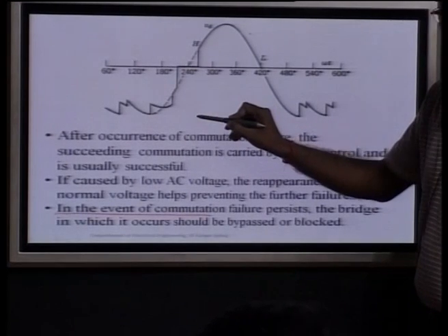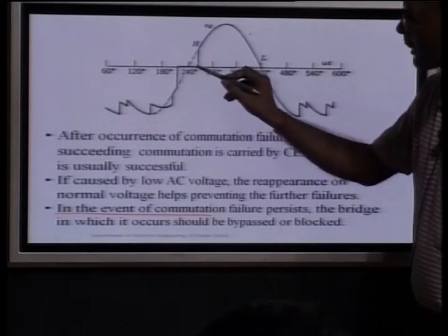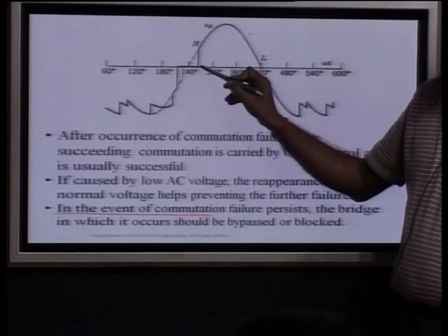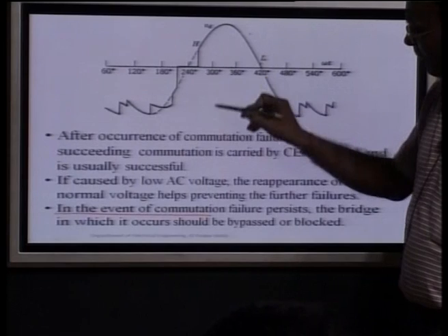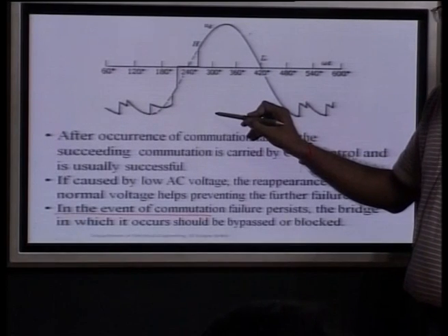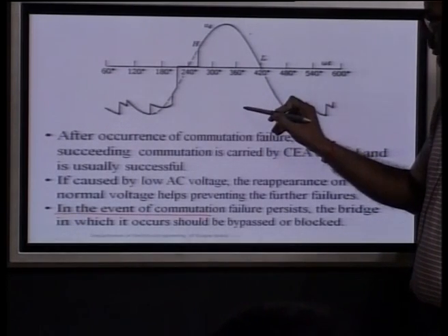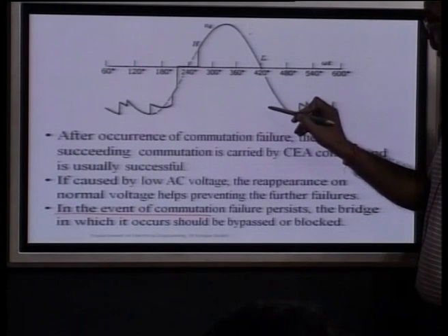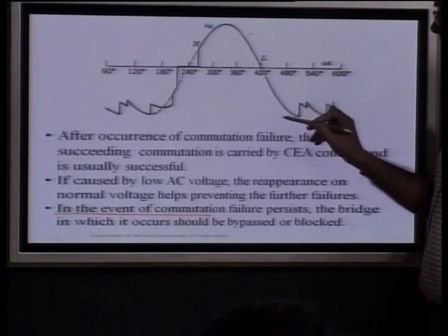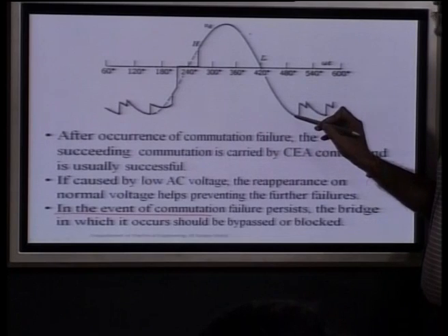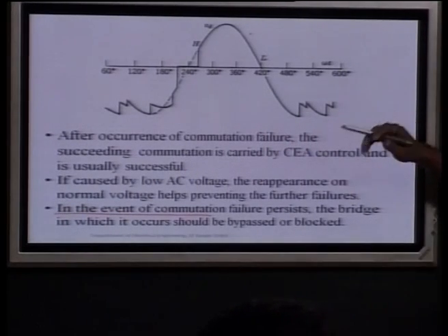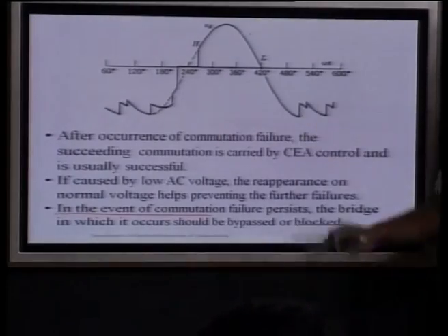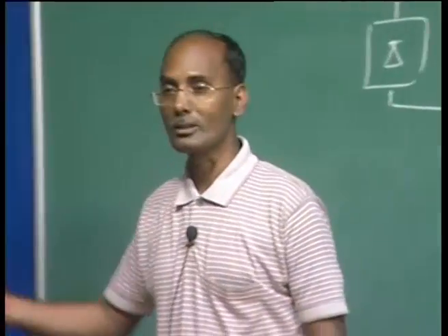Here the commutation was over, failing again between 2 and 4. Then the voltage came here, and we found here 5, because it is a negative voltage. Then we give 6 negative voltage, then we give 1, which was already conducting, then we give 2, which was already conducting, then here again we come to 3, and it continues. So here you can say in one cycle the average voltage is almost going to be 0 rather than negative, and that is a very severe case.